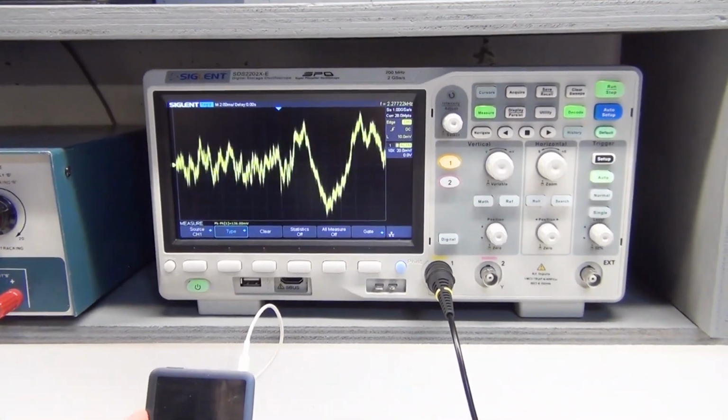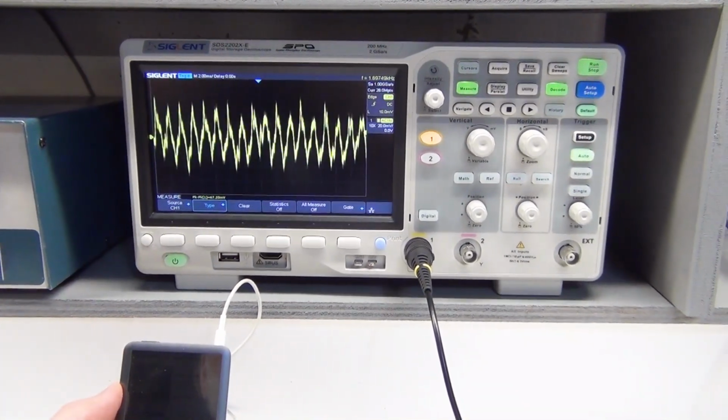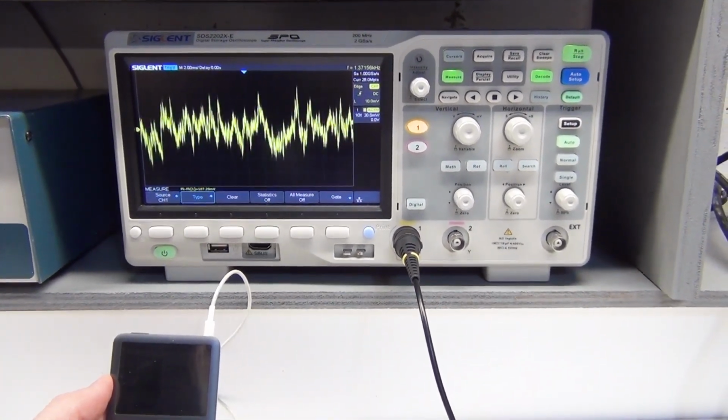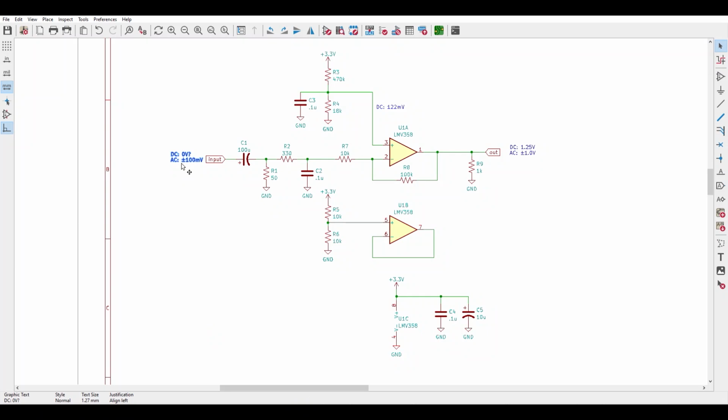Some quick testing shows that a signal at approximately mid-volume peaks at around plus or minus 100 millivolts when driving a 50 ohm load on each channel. And my Simpson can easily generate a plus or minus 100 millivolts signal at fixed frequencies. So that'll be my input criteria. And that's really convenient because that means I only need 10 times gain in my inverting op-amp circuit, which is easily achievable with 10K and 100K for R7 and R8.